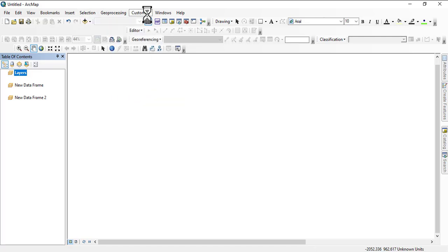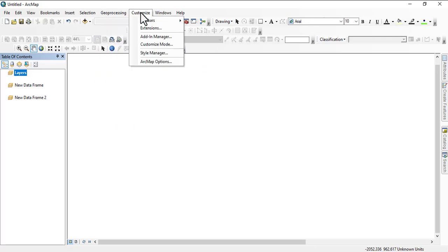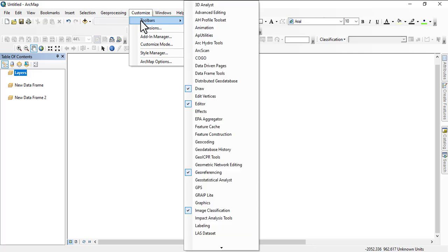Okay. And then we have geoprocessing tools, just like we looked at. And then we have buffer, clip, intersect, union, merge. You merge two, maybe you have 2 road layers, you can merge them into one. Clip is to just clip to your extent, but the clip in geoprocessing is basically using just shapefile, feature class, and all that. For raster, it has its own raster tool. And then all the tools that are in ArcMap, definitely ArcToolbox are in ArcToolbox and all that. So customize, you can also go to toolbar.